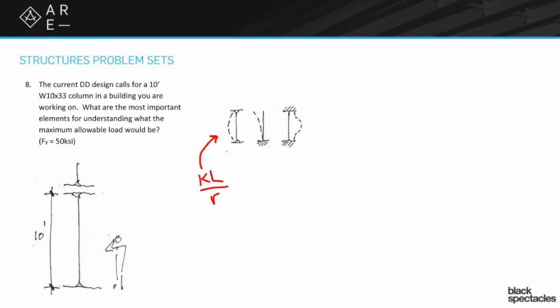It basically is having you think about what are my end conditions. This first one shows a pin-pin. The second one is a flagpole kind of condition, so it has a fixed base. And then the third one shows you 2 fixed ends. Because of the 2 fixed ends, as they come out of the fixity, they're coming out at 90 degrees, unlike the pin, which can rotate around. So you get a very different curving happening. So the value changes as you go through these. I happen to know that this pin is a 1.0, and I believe the cantilever is a 2.0. This one I have no idea off the top of my head. We'd have to look it up. But you can see how they change, depending on what fixity you have.